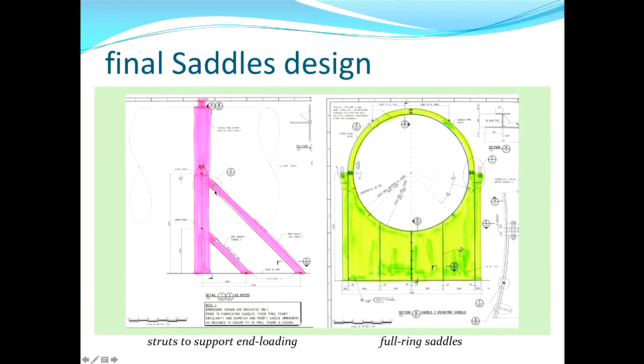We had to incorporate some serious props to resist the axial forces that occur in the pitching motion of the ship when it's sort of diving in headfirst into the waves. This 280-tonne prill tower is wanting to leap off the front of the ship. You've got to resist that. So we incorporated these props and did the calculations to make sure that they were adequate.